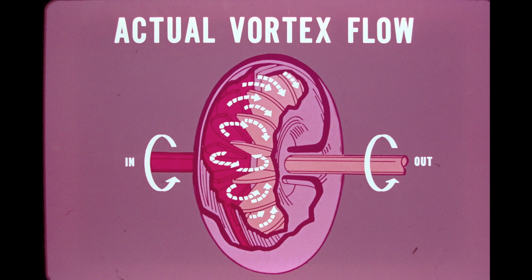As the engine begins to spin the impeller, the fluid begins traveling with the impeller, rotary fluid flow, and then centrifugal force ejects the fluid from the impeller. This is the beginning of vortex flow. The curvature of the impeller blades directs the fluid against the turbine blades with great force, rotating the turbine in the same direction as the impeller.